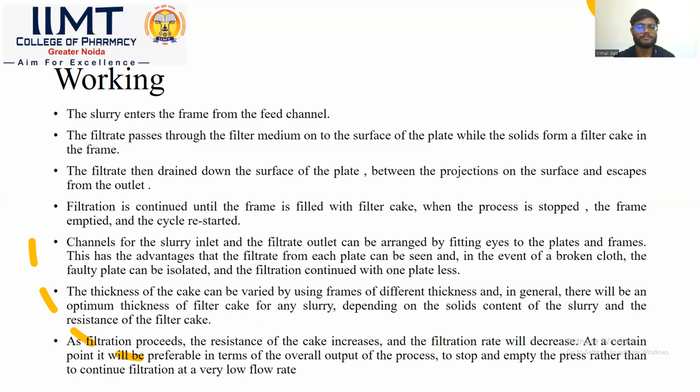As filtration proceeds, the resistance of the filter cake increases and the filtration rate decreases. At a certain point, it will be preferable in terms of the overall output of the process to stop and empty the press rather than to continue filtration at a very low flow rate.